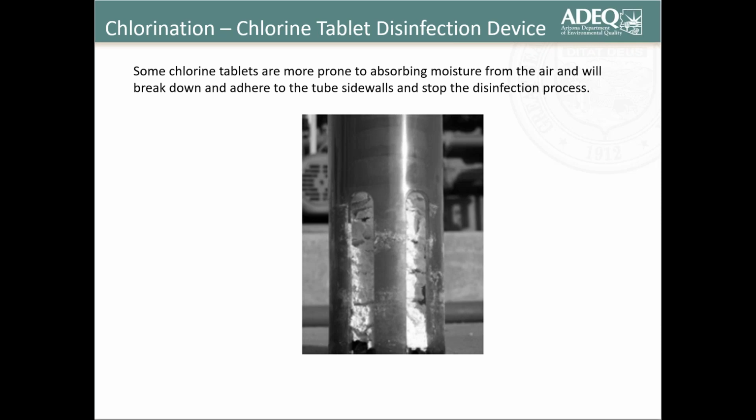I was talking with an individual that's an operator of these little on-site treatment plants and services and maintains them and so on. And he said this, he says, Raymond, I have found that the standard calcium hypochlorite tablet, 9 milligrams per liter dose, doesn't break down as much as the 20 milligram per liter tablet.